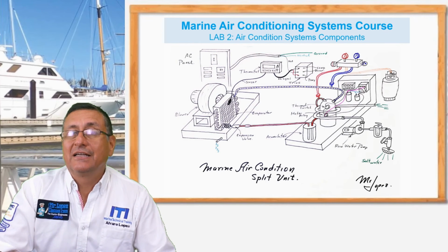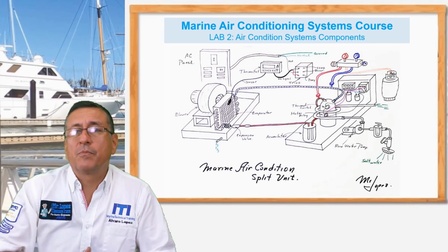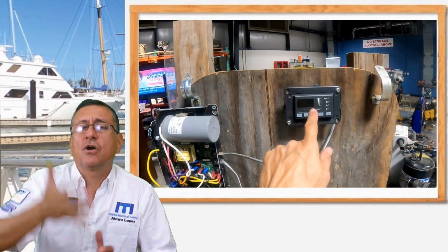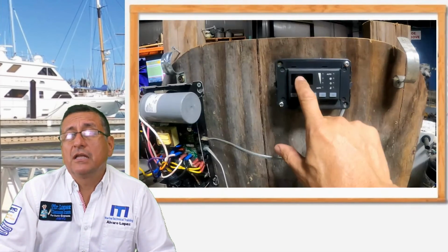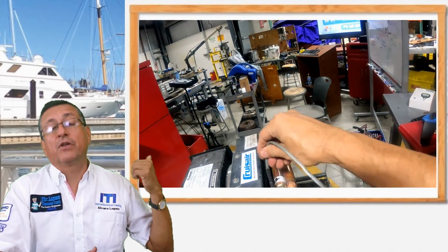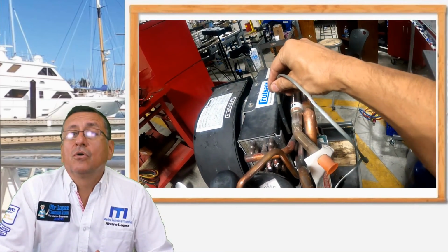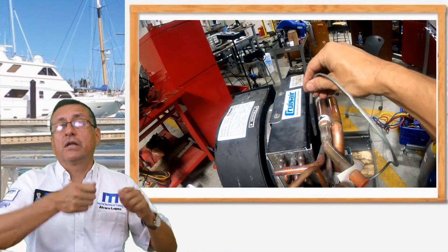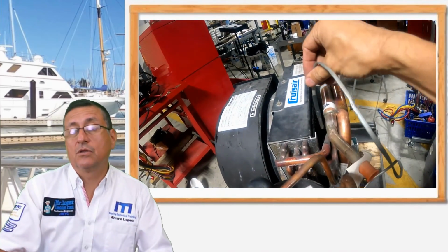All right, those are the most common problems. Another common problem is my thermostat doesn't respond. Probably the batteries on the thermostat are out, or probably the signal coming from the evaporator in front of the filter, the sensor, is out, or the cable is broken, the data cable is broken, and you need to fix those elements.